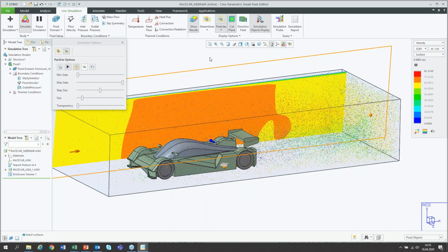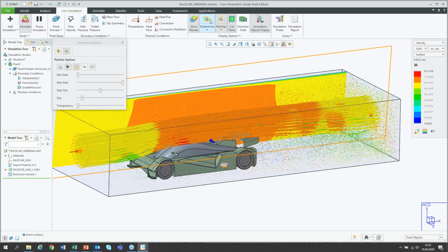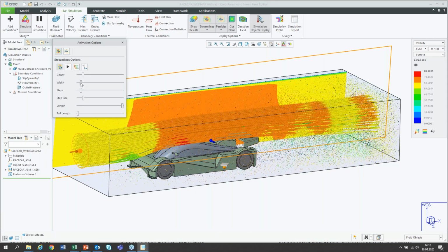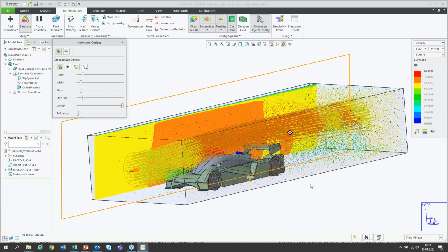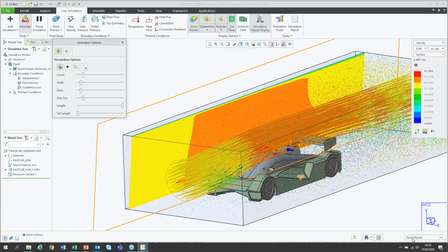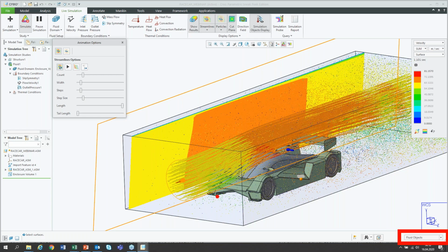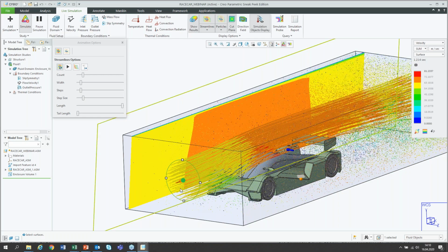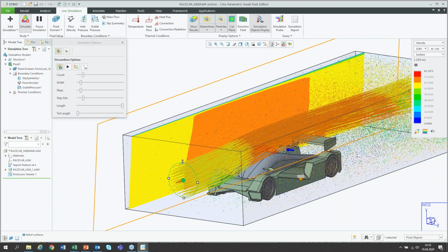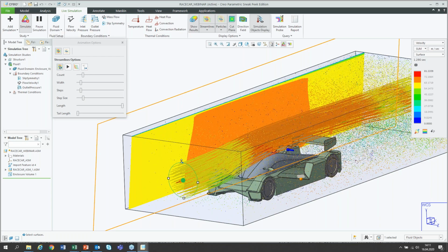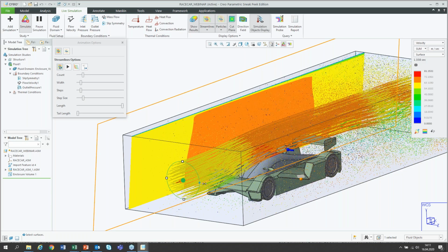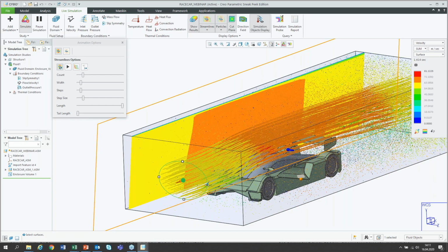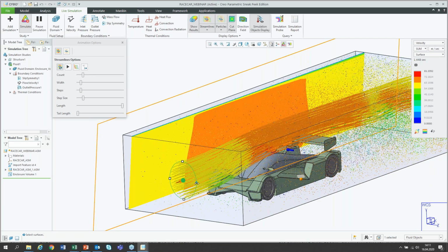Okay, and I want to see also the streamlines. Size of streamlines, make the width a little bit smaller. Okay, doesn't look that bad. And here the fluid objects are selected with the filter, therefore I can just double click that one and influence it. Holding down the shift button, it will be scaled. Holding down the control button, I have the ellipse behavior, and holding down nothing, it's also the ellipse behavior.